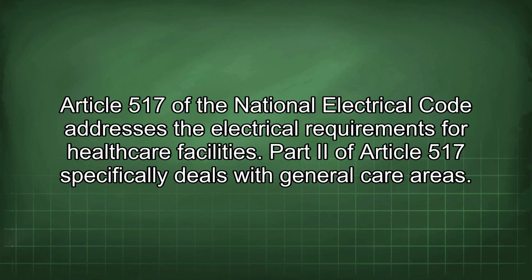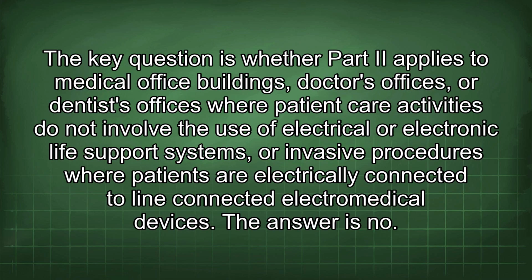Article 517 of the National Electrical Code addresses the electrical requirements for healthcare facilities. Part II of Article 517 specifically deals with general care areas. The key question is whether Part II applies to medical office buildings, doctors' offices, or dentist offices where patient care activities do not involve the use of electrical or electronic life support systems, or invasive procedures where patients are electrically connected to line-connected electromedical devices.